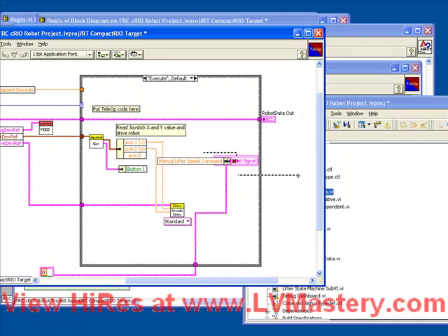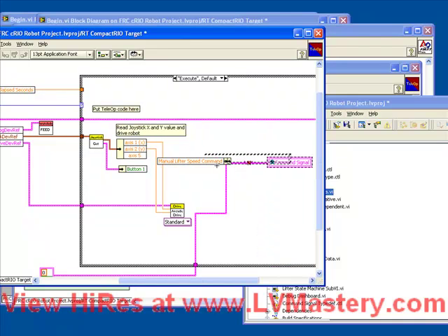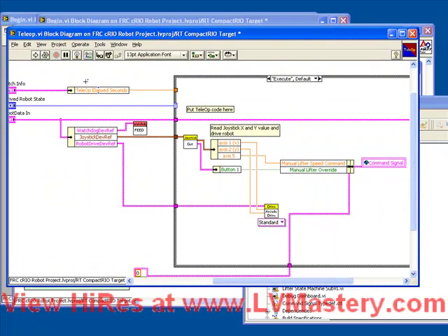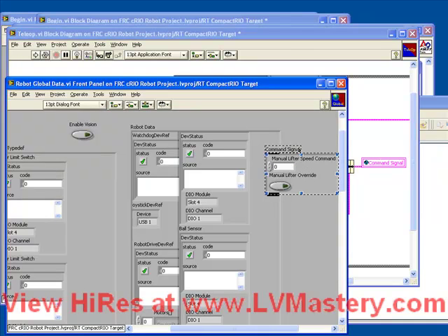Because we've chosen such long names, we'll just expand to get a little bit more room. And hook up axis 5 to our manual lifter speed command and button 1 to our manual lifter override. If we had other loops that cared about the information from the Tele-Op, then we could add those values into our command signal type def.